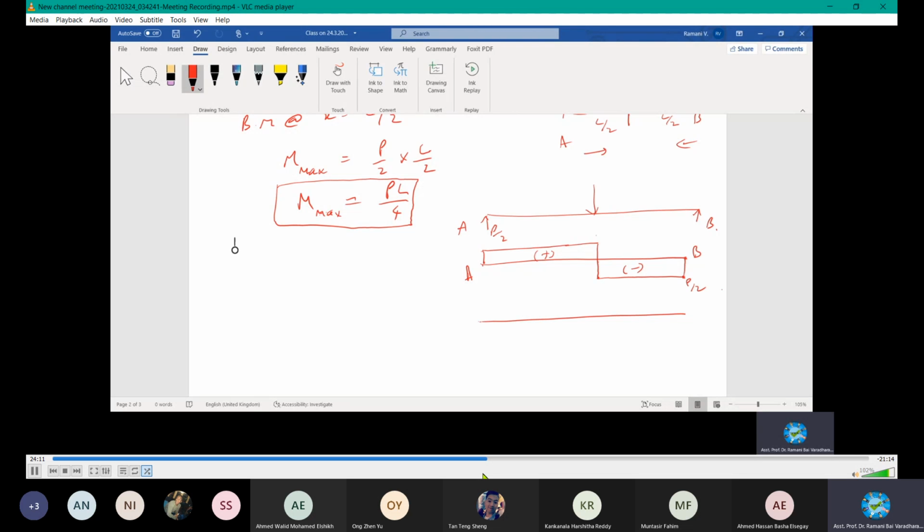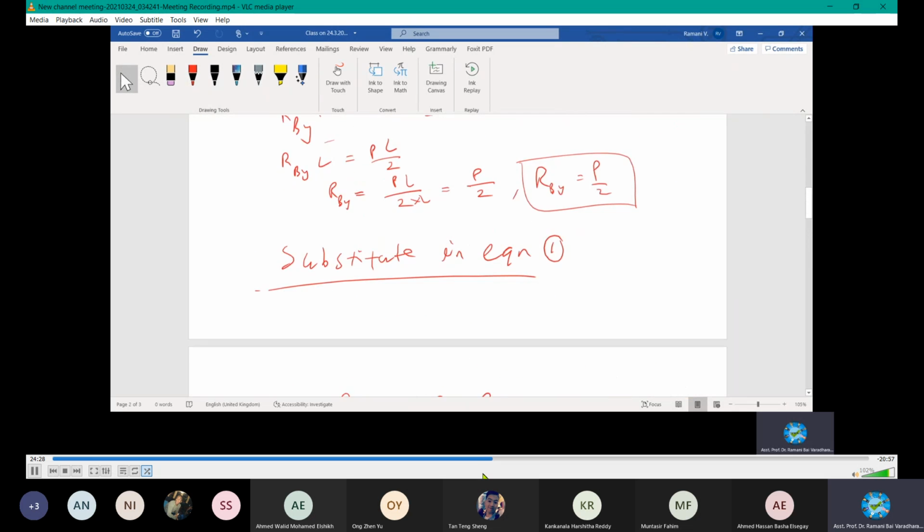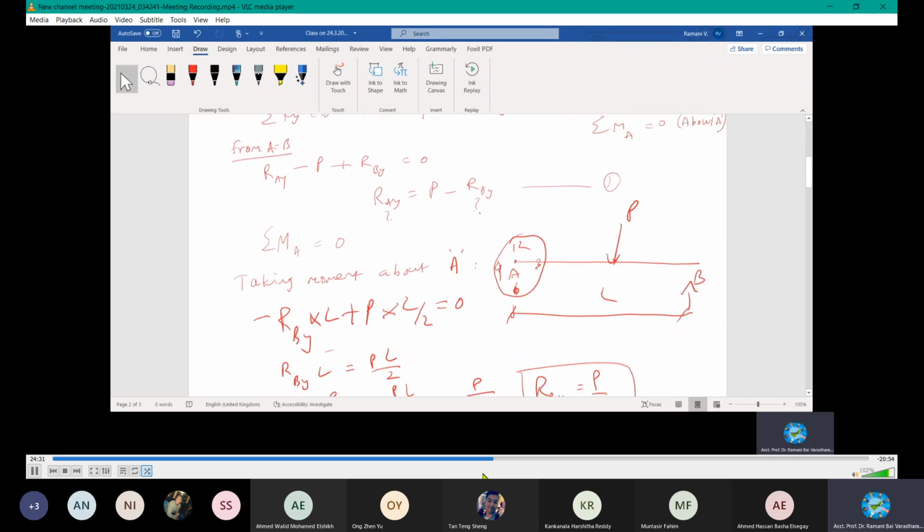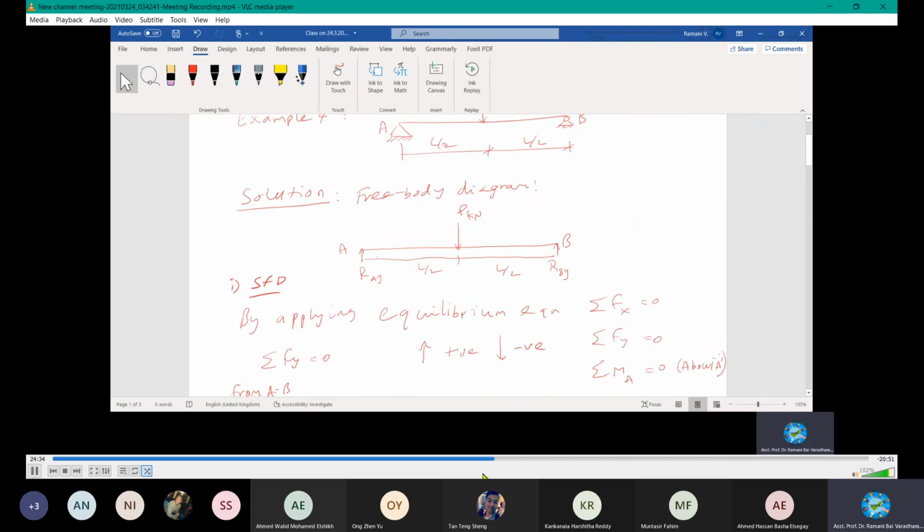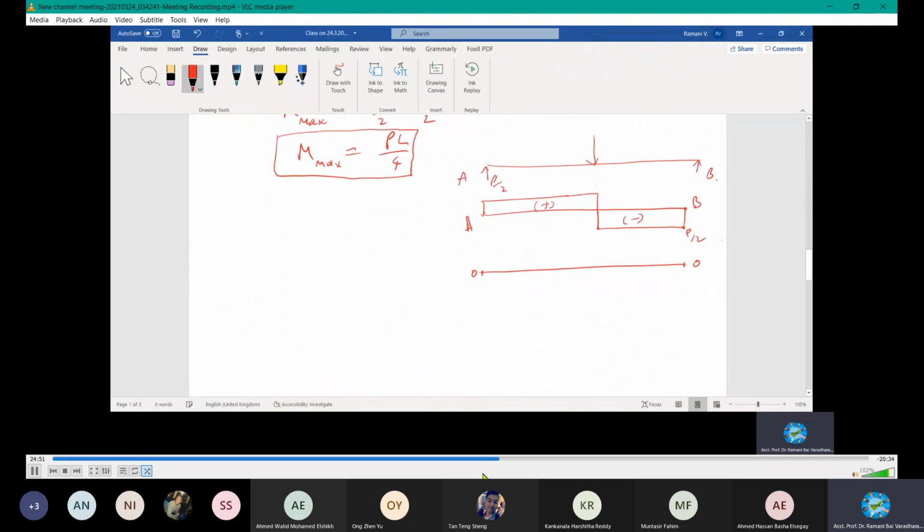And then this is the shear force. Now the bending moment diagram. Oh, how much is the value at the end? Because it's simply supported, the moments are 0. Just now we solved also, we got the 0 value, right? And then the maximum occurs at the middle, positive or negative. With this type of loading, you can simply say it is hogging or sagging by observation, because it is one load, right? It's a type of sagging, which is positive, right? So positive we put downward.